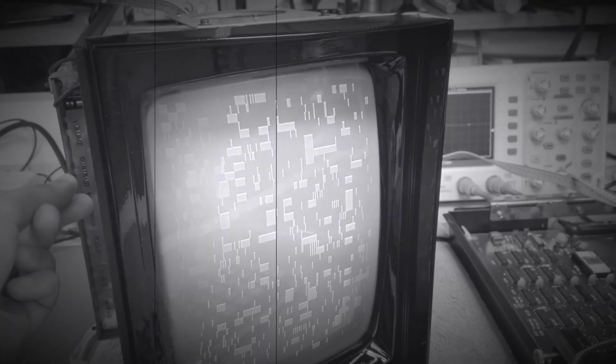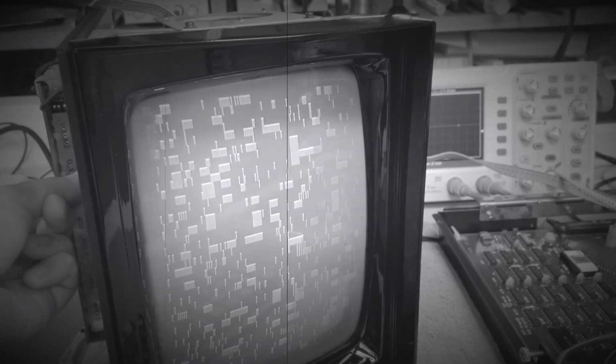screen. Number one, the CPU is not managing to clear screen memory. That's why we see this garble. Number two, either character generation or the shift register that spits out the individual bits of every character byte towards the screen are not working, one of the two. And that's why we only see lines and not well-formed characters on the screen. We should keep this in mind.